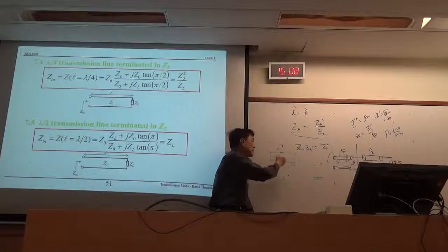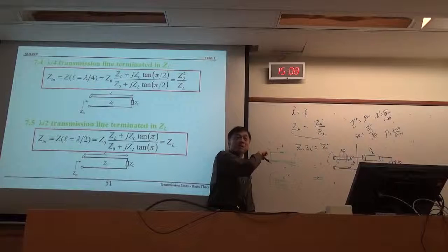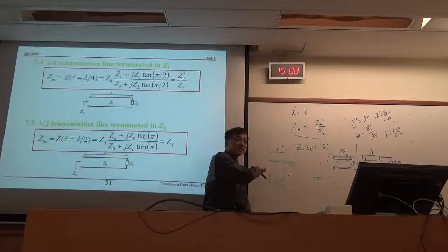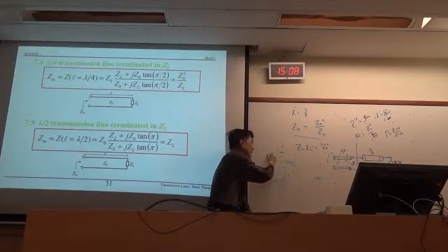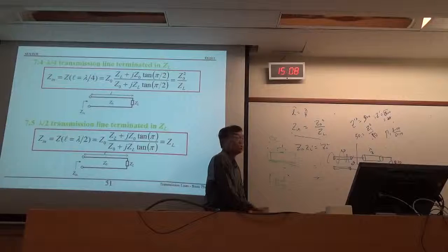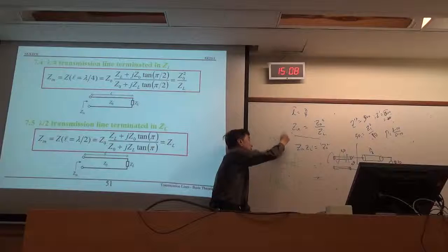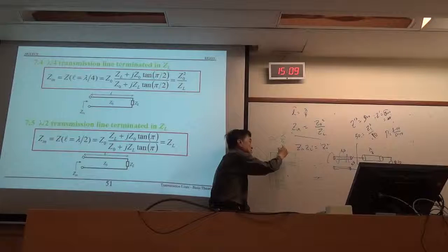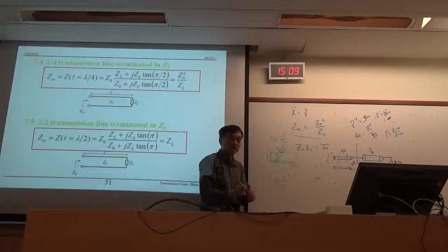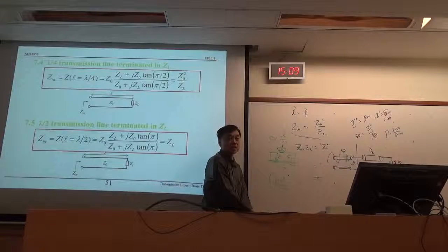This is also a transmission line. Right from the beginning, we introduced this as a kind of transmission line. Now, the characteristic impedance of this kind of transmission line is proportional to the thickness of the substrate h over the width W, and also depends on epsilon r of the substrate.